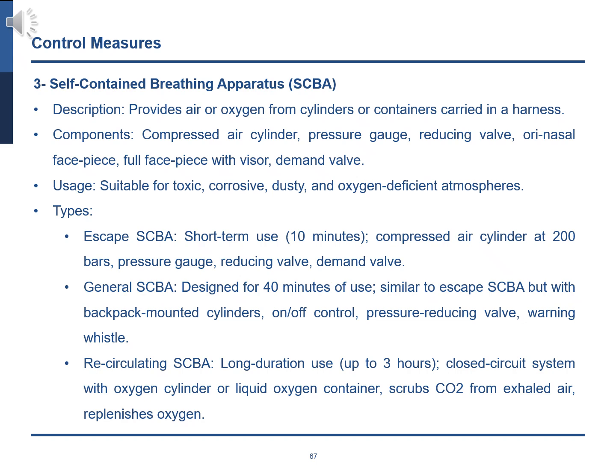General SCBA, designed for 40 minutes of use, similar to Escape SCBA but with backpack-mounted cylinders, on-off control, pressure-reducing valve, warning whistle. Recirculating SCBA, long-duration use, up to 3 hours, closed-circuit system with oxygen cylinder or liquid oxygen container, scrubs CO2 from exhaled air, replenishes oxygen.